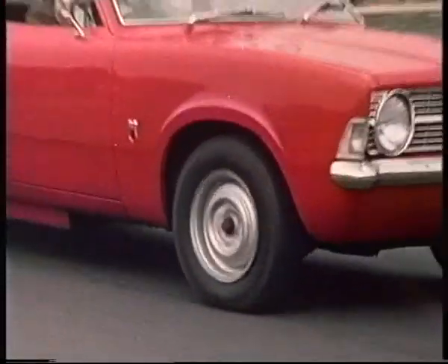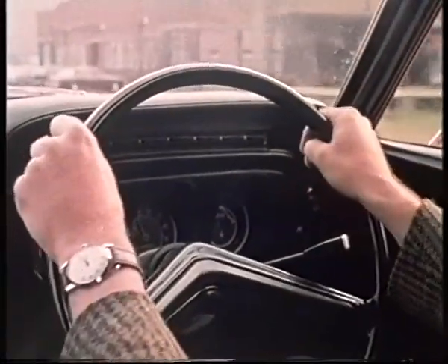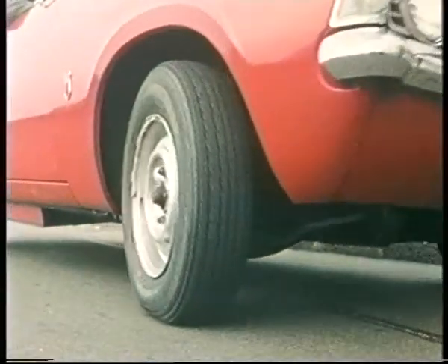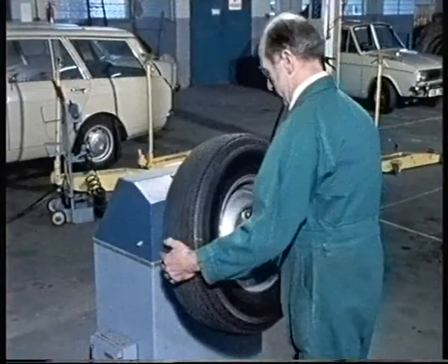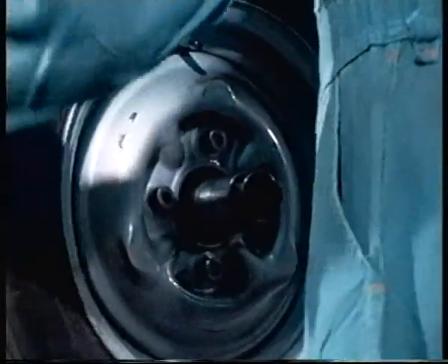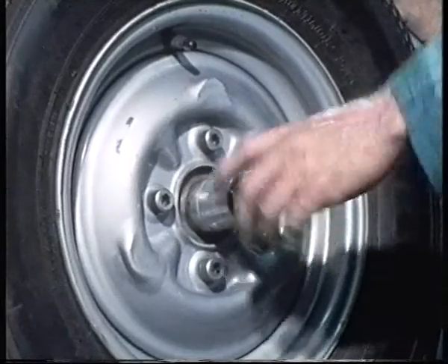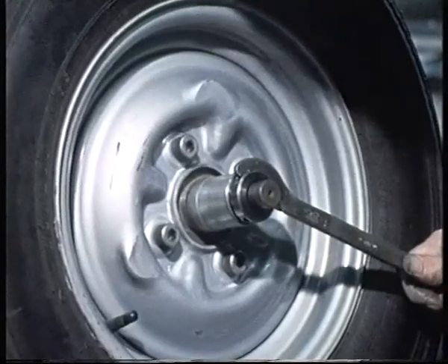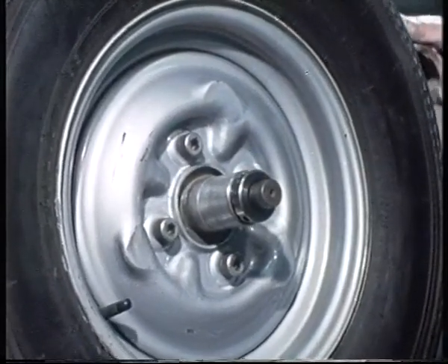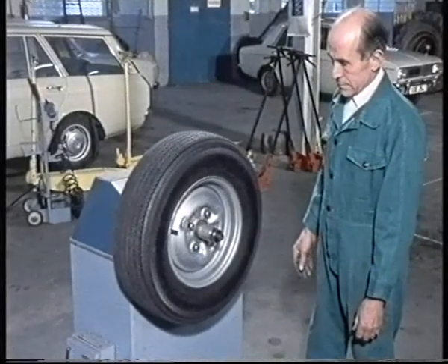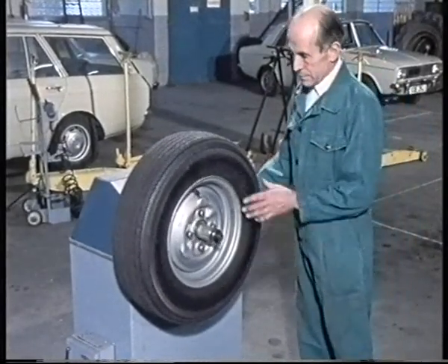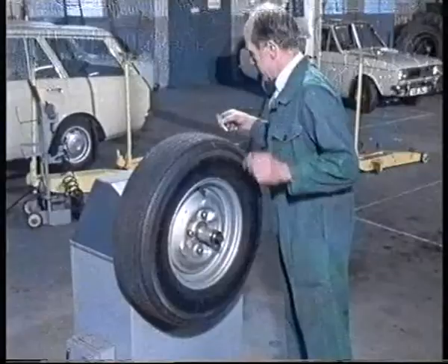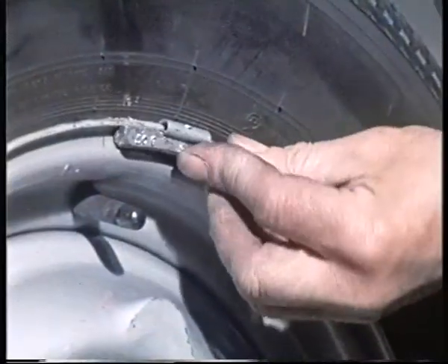But this wheel isn't. And that's not too good for the car or the driver. Balancing up a car wheel is very like balancing the faceplate. First, you mount the wheel on a spindle. Then you let it go to see where the extra weight is needed. And just as before, you add on an extra weight to get the wheel in balance.